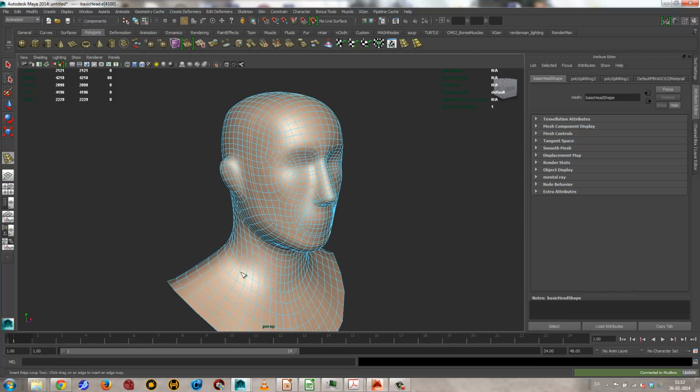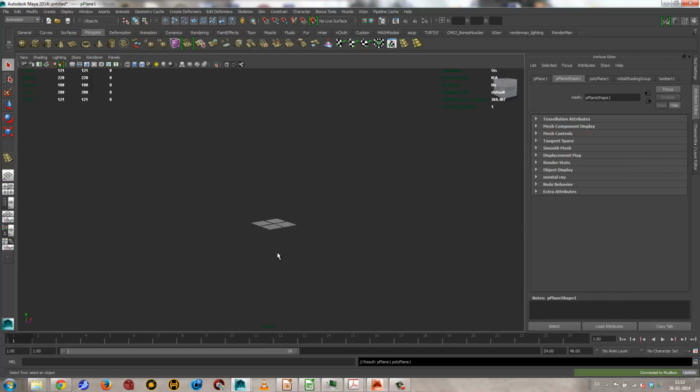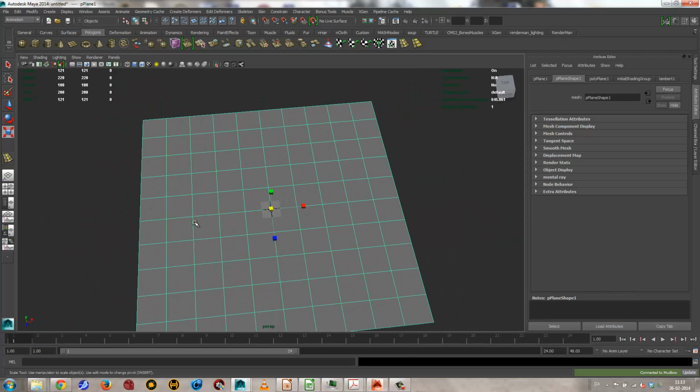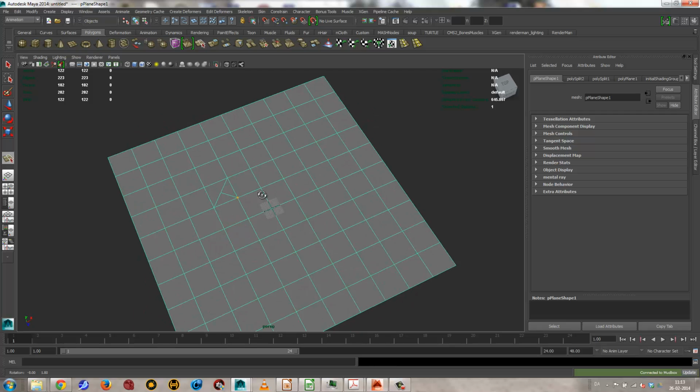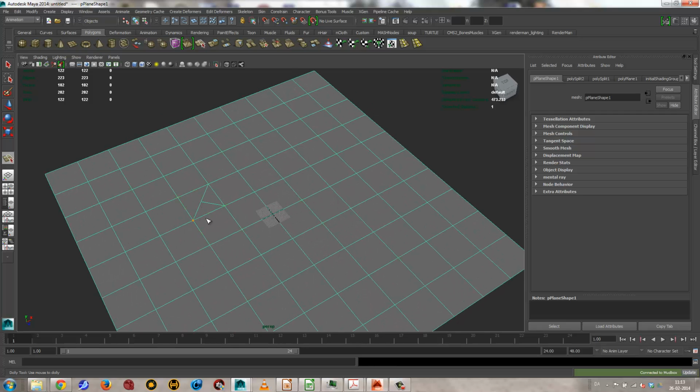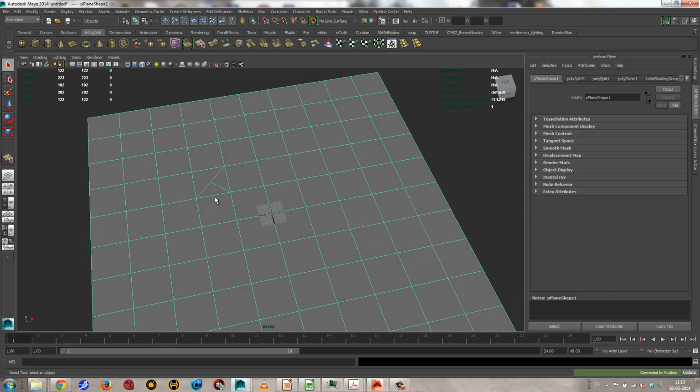So edge loops are very useful, but the whole thought process that goes on there is to think about your model as a grid, and then you need to realign it so that you can control where your curves are going. So if I, for instance, wanted a loop going around this way here, then what I would need to do is grab my split tool here and say, okay, I want it to go this way. So this created a triangle. I don't want that. This should be a square. So something like this perhaps. So now this is a square, but this is not. So that's one of the things I would have to consider.